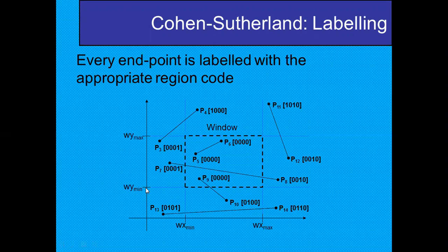Now another window parameter, wy min. So put again here from the origin count. Suppose this is 5 again. Then draw a horizontal line, again at 90-degree, just a straight line. And again put here, suppose this is 30. Wy max 30 means the fourth parameter of your window. Then suppose from the origin this is 30 units. Then again draw this straight line.